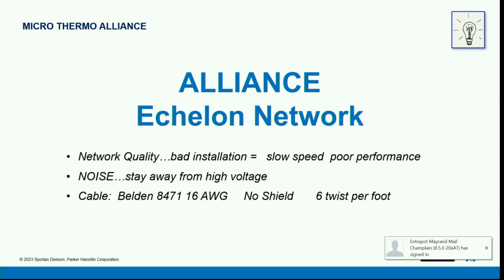You're going to have nodes that are appearing and disappearing. I can't stress that enough. Noise: stay away from high voltage, okay? And that includes 24 volts. Don't run network wiring in the same conduit with 24 volts, 120, 208, 460. Free air it, keep it by itself, okay?